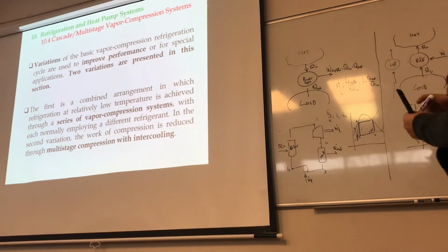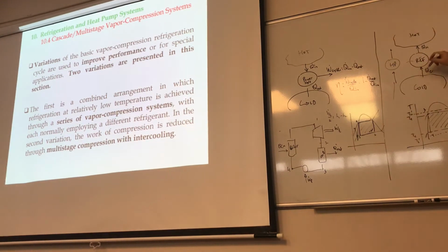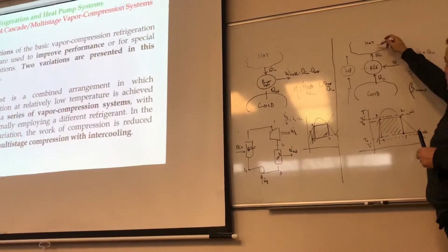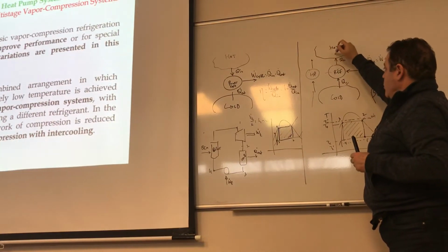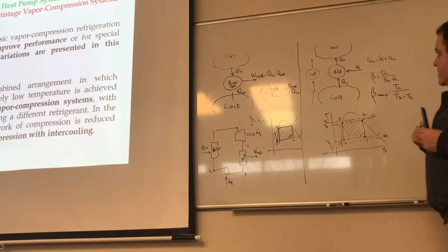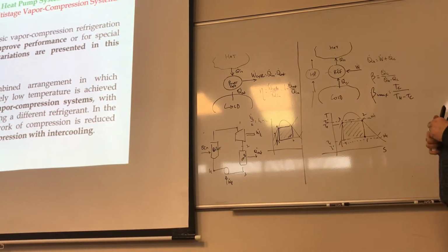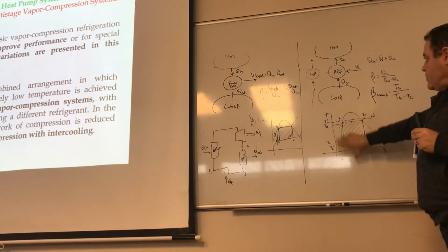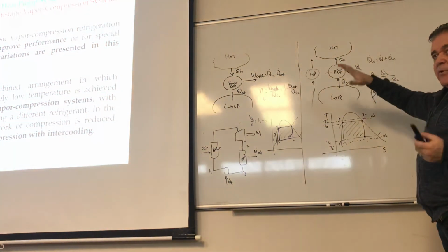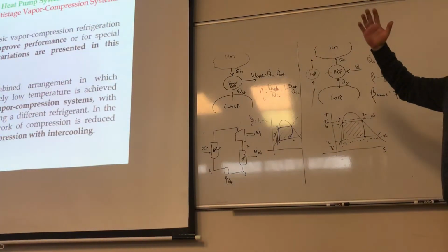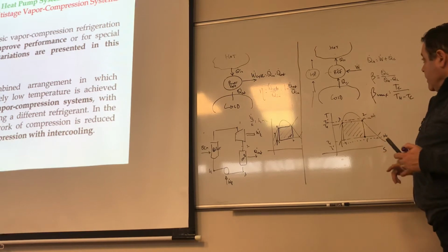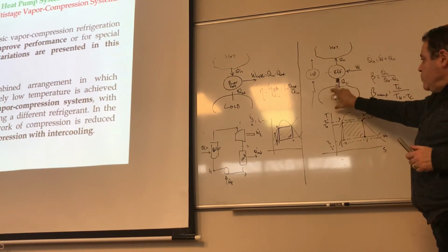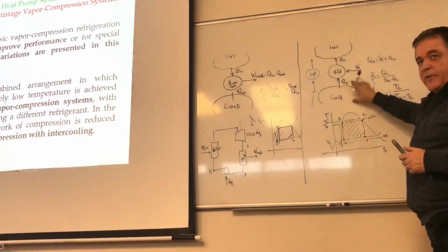and we've seen this in vapor power cycles too. Remember here what we have? We have, let's say, a refrigerant. You are removing heat in here, right? And you are dumping the whole thing in here. So what happens as you have one vapor cycle in series with another one? Both of those obviously have to operate at different temperatures. Maybe you're going to have a low temperature one here, another high temperature one, right? And then what's going to link them is really what's happening here in between.